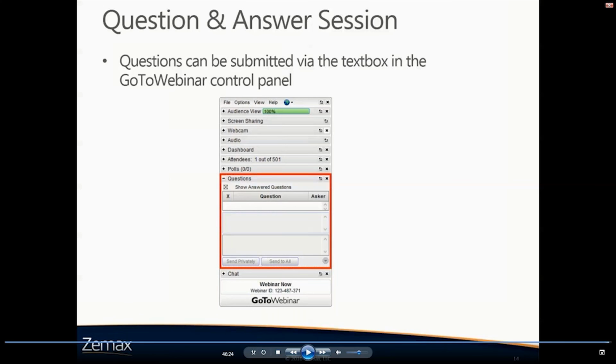Alternatively, if that doesn't work, there are some other workarounds you could consider. I haven't thought through them fully, but it could be something like having two objects that are extremely similar in size, one slightly inside the other. One interface would have a Lambertian and the other interface would have the ABg scatter profile. There could be some risk in getting rays that bounce back and forth between the two. They probably wouldn't TIR because you'd want them to be made of the same material. So I'd have to think through that one, but there are probably some workarounds we could make work.